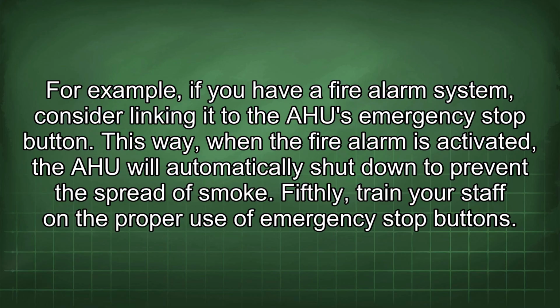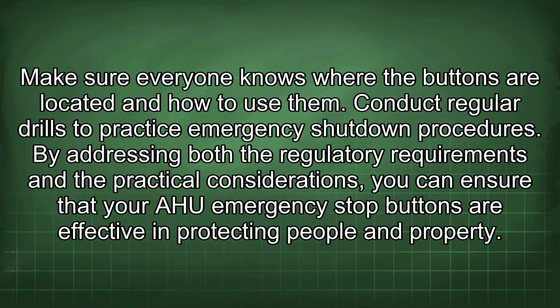Fifthly, train your staff on the proper use of emergency stop buttons. Make sure everyone knows where the buttons are located and how to use them. Conduct regular drills to practice emergency shutdown procedures.